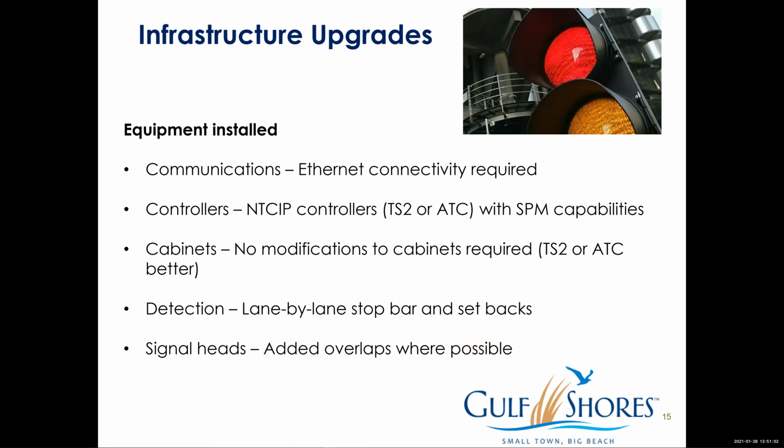So in order to get this to work, we had to make sure that we had good Ethernet connectivity between each intersection and that we could get the data back and that it was a constant and steady flow of information. The controllers we used were NTCIP. They're ATC controllers with SPM capabilities. Just about every controller out there these days has the ability to record SPM data as long as it's NTCIP compliant and we can grab the data.